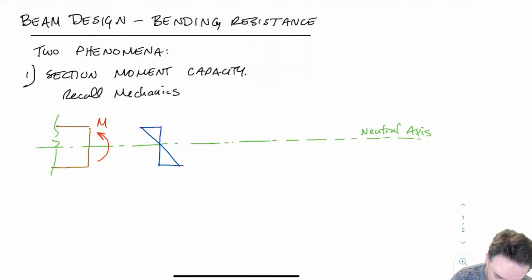So here I have the strain, and our strain profile is linear. And remember, typically for typical members in construction, we are assuming that these members are Euler-Bernoulli beams, so that plane sections remain plane, and our strain profile throughout the depth is totally linear, and we have compression on the top in this case and tension in the bottom, and in between our strain has a linear profile, and at the center where we have the neutral axis we have zero strain.